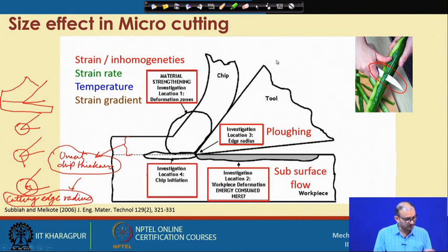and this is the chip initiation, that is also important, because when you want to remove some material, this is the chip, whatever is coming from here; these are the chips in terms of our routine operation. And here what is important is how to initiate the chip, because chip initiation occurs at some particular defects. Suppose your material has something here. These are the grains located here, there are some porosities available here, some inclusions are also there, some foreign material is available. If it is an alloy, then there are different hardness, hard phases available in that. So, these are the different types of defects we consider.